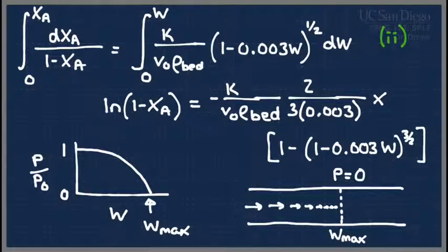That's an upper limit you'll want to keep an eye on for your project, because some of the way that your project has been worded for some of those problems is run the simulation until a number of different events occur. One of the events that can occur is that the pressure drops below some minimum pressure. Usually that minimum, if you're dealing with gauge pressure, is 0. If you're dealing with absolutes, it's usually 1, because at that point your pump isn't doing anything anymore, it's just atmospheric pressure.